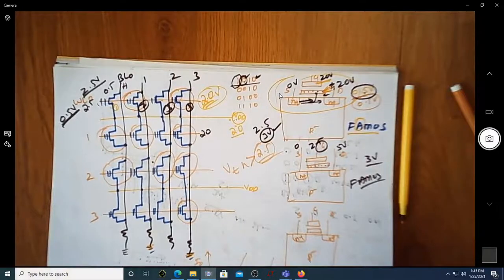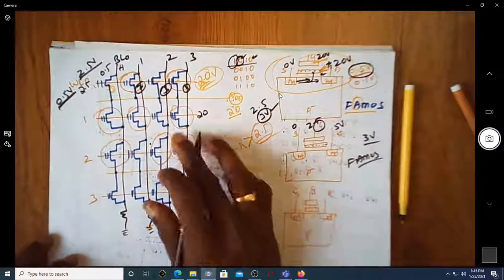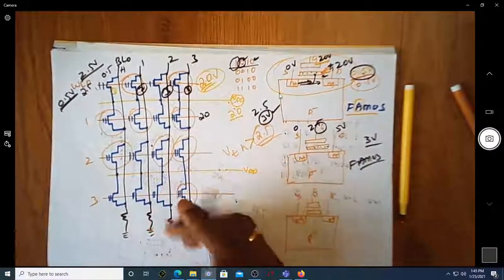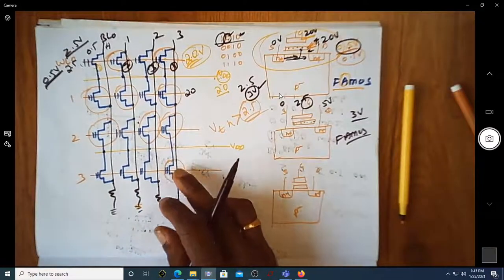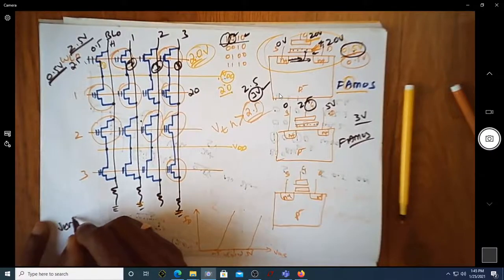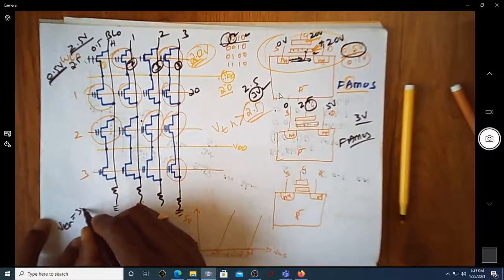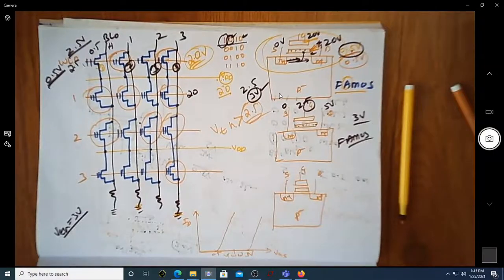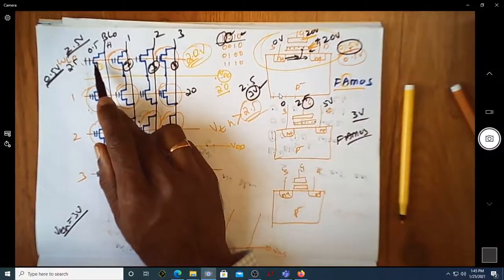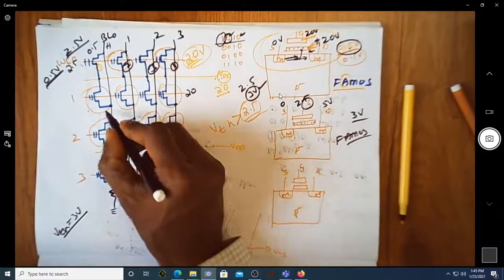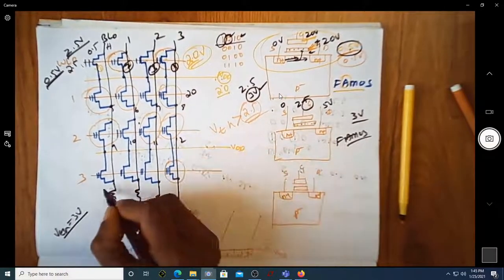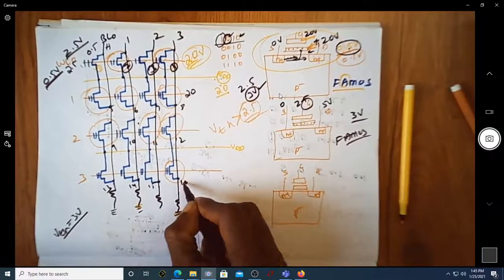the enhanced threshold voltage. Okay, once we make the corresponding rows and columns and VDD as the required voltages, the transistors which are rounded up will have a larger threshold voltage. Assume that the VTH of those transistors which are rounded up are made equal to 3 volt. So meaning, out of 16 transistors, transistor number 1, let me just take, this is 4, 5, 6, 7, 8, 9, 10, 11, 12, 13, 14, 15, 16.